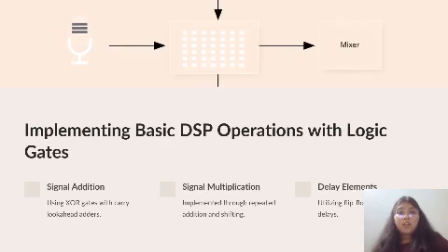Logic gate based audio filtering. Filter design: a low pass filter allows low frequencies to pass while blocking higher ones. We first decide the cutoff frequency, meaning at what point higher frequencies should be removed. This way we can allow only desired frequencies to pass through. Testing: once the filter is built, we test it to check the frequency response, how well it blocks or allows the different frequencies.